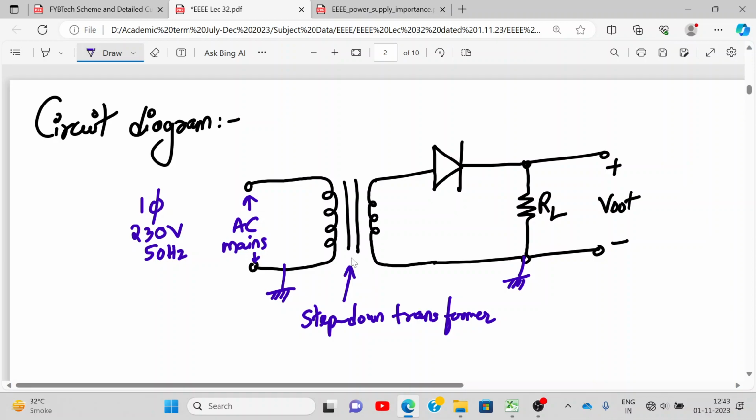So it will prevent you, if you are touching the other part of the circuit and your transformer is on, from getting a shock, because the grounds of both are different. Are you understanding? If grounds are same, what will happen? The current which is flowing over there might interact with the remaining part of the circuit, and whoever is handling it may get a shock if they are not careful. Is this okay? Fine. Now, this is my diode circuit.